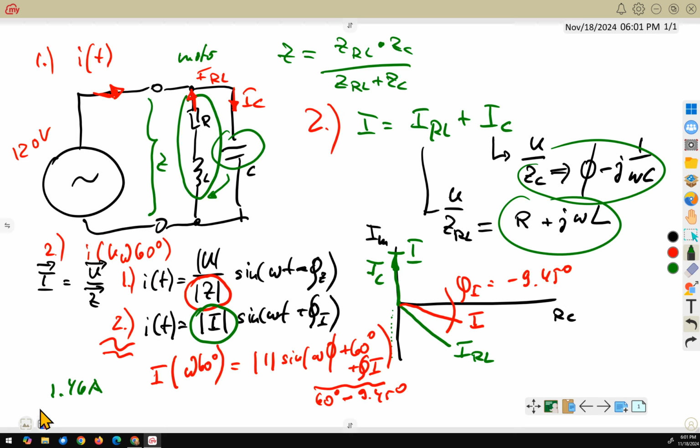What's very important to know, this value here is the peak voltage, and the peak voltage is actually the real momentary value. The voltage given to us here is in RMS, and you would know the relation between effective or RMS voltage and peak voltage is the square root of 2. Therefore, we do all the calculations with the effective voltage, the RMS values, but at the end we have to multiply our results by the square root of 2 in order to get the real peak value.